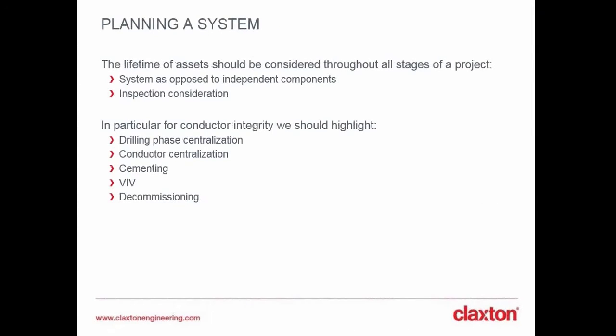The design life of equipment, typically for the offshore industry, is set to about 20 to 25 years for structural elements on offshore platforms, which should be, in theory, the minimum time the equipment should be able to reach in working conditions. But as we discussed before, the conditions under which the equipment was originally designed might have changed, so part of that initial stage should consider likely changes and modifications, if possible, as well.